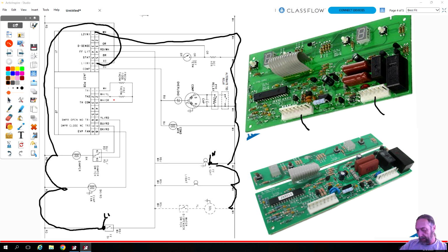Now the board's not lighting up at all. That's what happened to me at TMM, guys. The board wasn't working, and just now it was working with you guys for the first time. It only works when I connect the light switch. Let me see something here. I've never seen that before. It may be backfeeding through the light switch because it's not in the wiring harness of the machine.